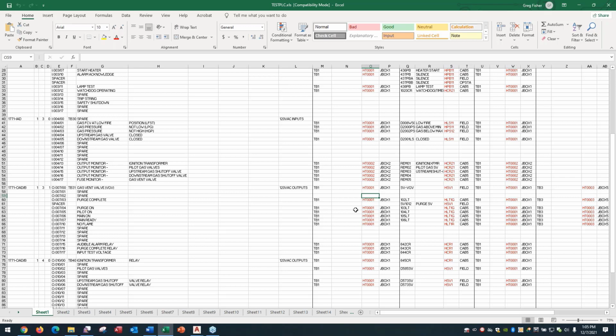That makes perfect sense. Okay, so I think you addressed this, but Michael has a question. Can you use custom IO module blocks as a template instead of the default? So, for example, we've dealt with some company standards where they place a rectangle around the IO point text. Yeah, there's nothing that's going to place a box around the text. If you're talking about the location code box, where you can wrap it around multiple components, you would have to do that after it goes through the utility. It's not part of the utility.